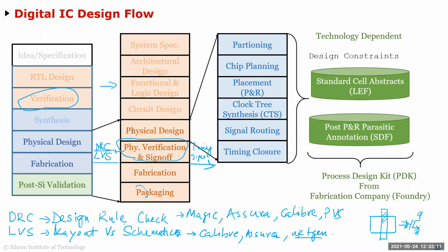It'll be clear when we do the delays. Now, the delay will change depending on the data, but you design it for worst case, right? Because you don't know what the delay is going to be. So all this timing sign off, which I'm showing here, they are meant for worst case delays. Okay. So basically, you design for worst case delays.